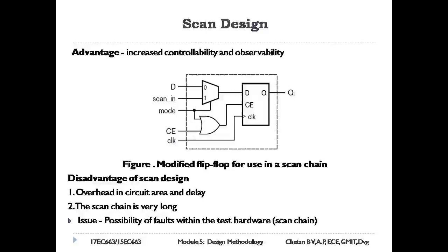Disadvantages of scan design. The first disadvantage is overhead in circuit area and delay. Modified flip-flops have additional circuitry including an input multiplexer. An input multiplexer imposes additional delay in the combinational path leading to the flip-flop input. If the path is a critical timing path, performance of the whole system is affected.